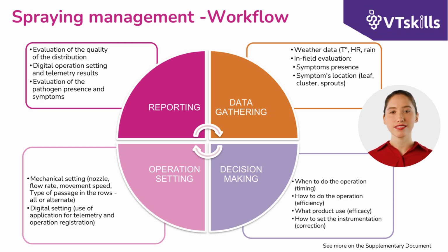Phase 3 consists of the configuration of the executive phase of the application, spraying band, parameters of forward speed and volume applied per hectare, and the logistics of passage within the vineyard. These parameters are recorded either on the onboard terminals of tractors equipped with ISOBUS systems or on dedicated terminals for digitized support of the application of plant protection products. It is therefore necessary to configure the digital technology to operate the sprayer according to the desired parameters.